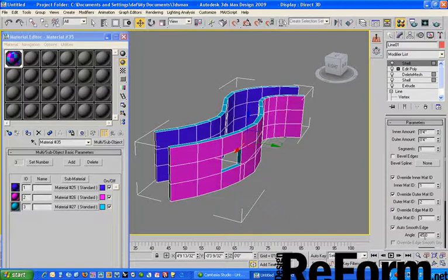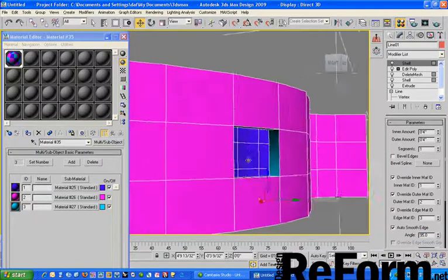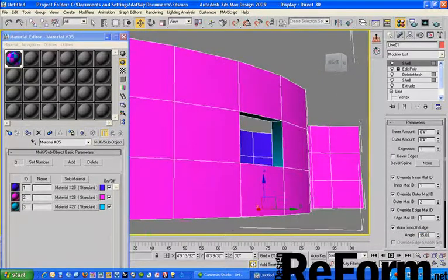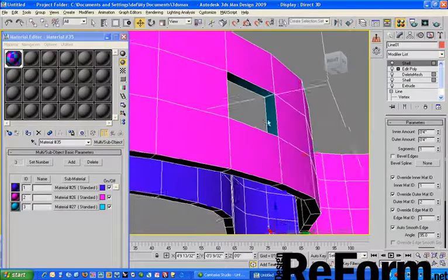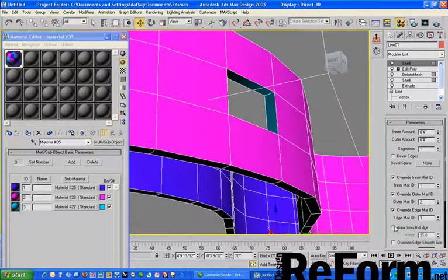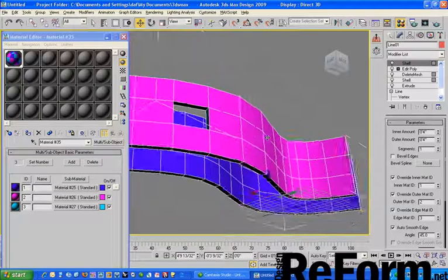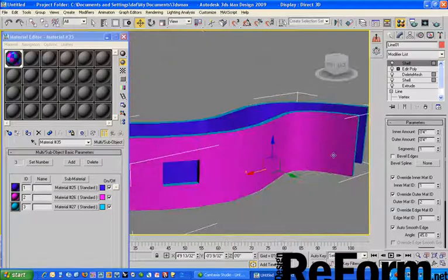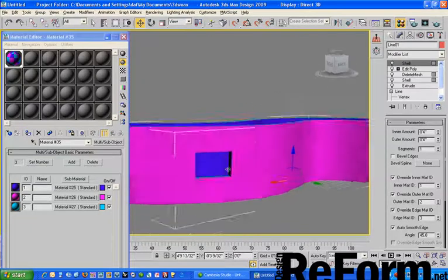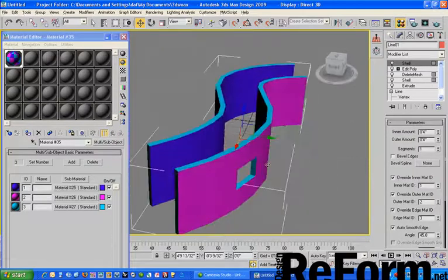Now the smoothing here, edge smoothing, if I bring this up to, let's say, 95, so anything under 90 degrees, or two faces under 90 degrees from each other, will start to automatically smooth. So you can either turn that off, or let's bring it down to 45 degrees, which is the default. So all of these we can see are graphically smoothed, but then the edges are not.